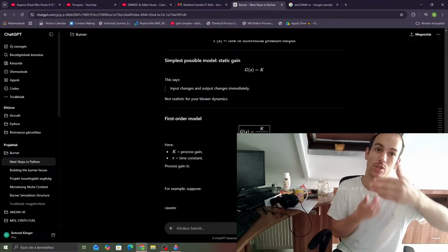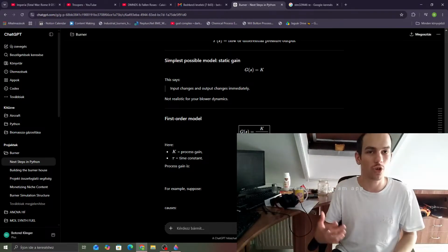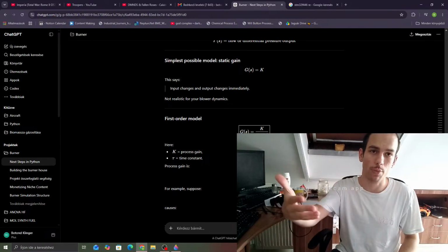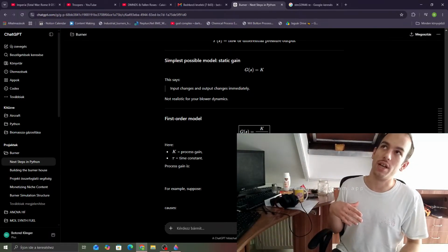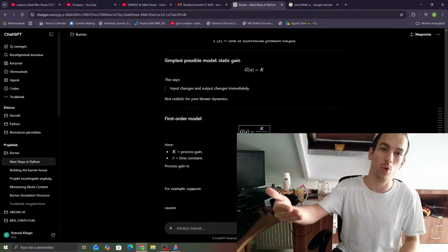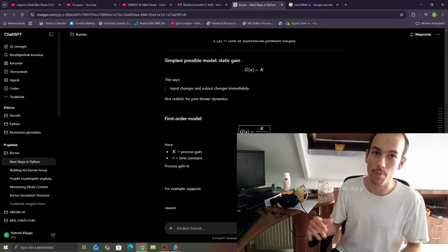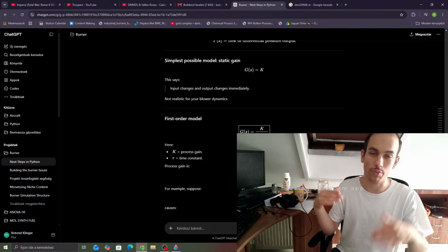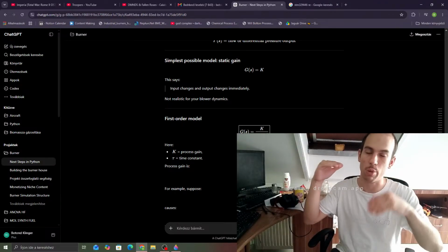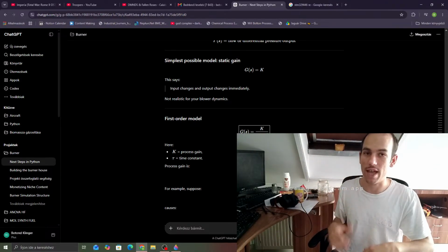It can increase the PWM because it sees that the temperature changed, therefore the viscosity gets lower and it pumps more fuel, which is not necessary, so it will lower the amount of PWM, and then it has the exact same amount of fuel and the exact same amount of air, and it does that with the air as well.